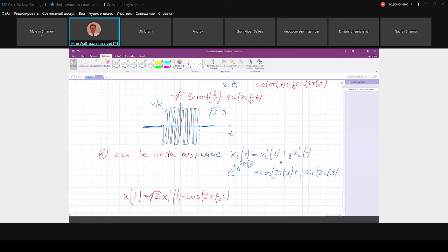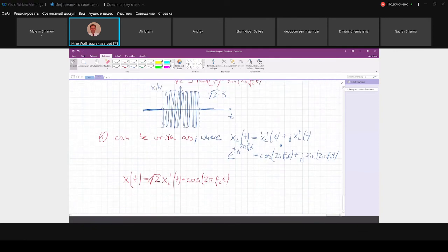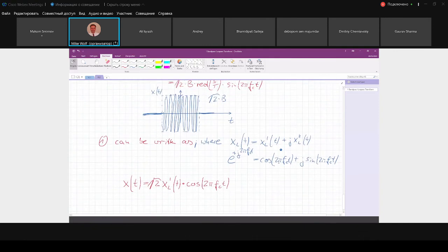This can be interpreted as the real part of our complex signal, but this is just an interpretation. And then look, this times this becomes imaginary. So it's this j, but to take the real part, there is no combination of this and this. There's also no combination of the cosine carrier and this, because this is a j. But here we have j times j. This times this becomes -1.